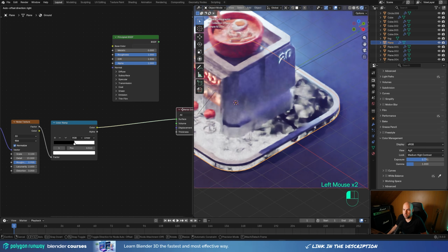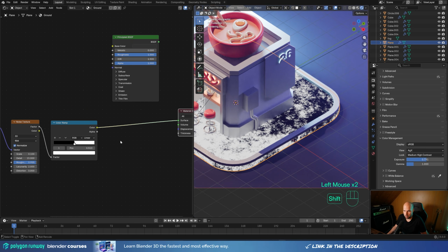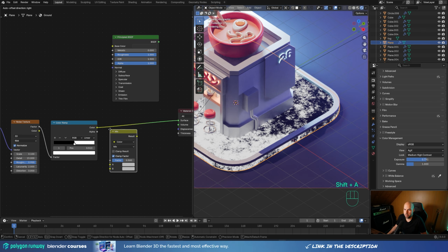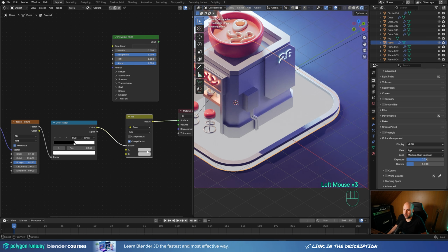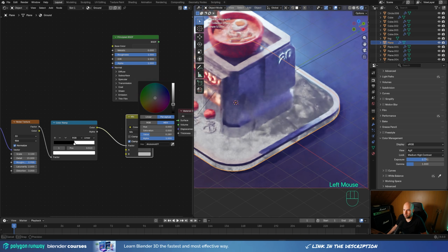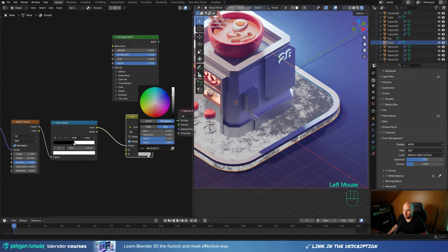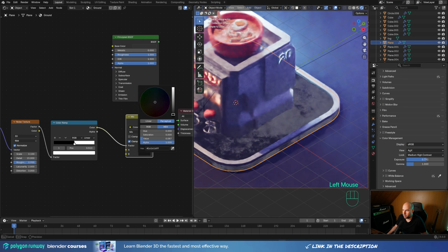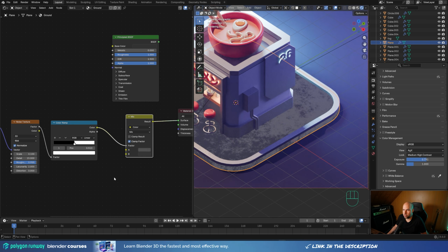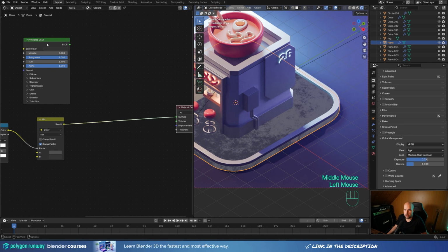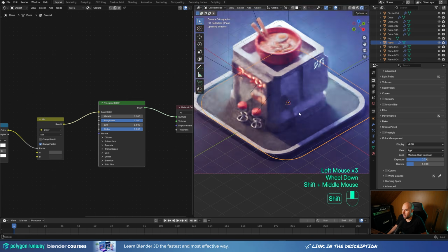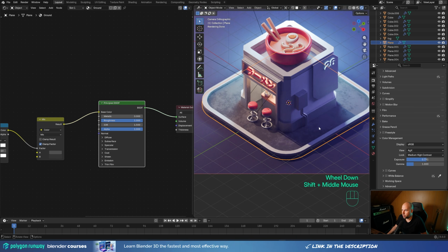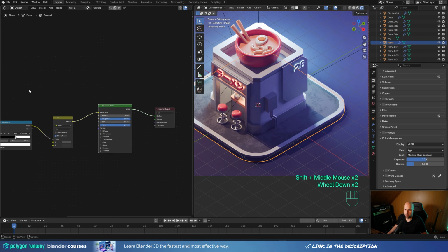And then you can just use something like a mix color node. So let's press Shift A, let's do mix color, plug it here, but you need to go into the factor. And here you can basically just make this dark as it was, and now use different color here to mix these together. Something really subtle should work okay. And now you can just plug the principal shader again, it will plug into the base color, and you will get something much more interesting than before.